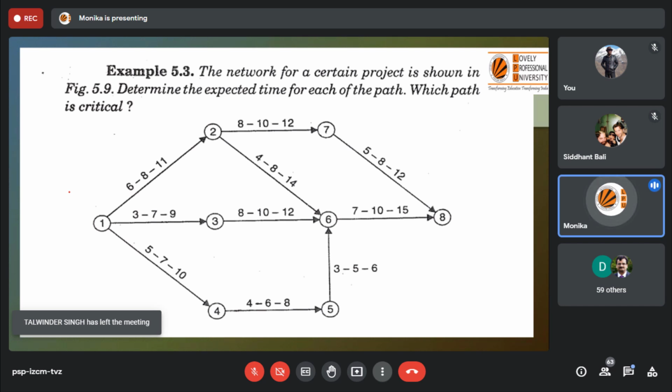Because sometimes everything is in favor of a particular activity. That's why we are not considering the whole project; we are considering it activity-wise. Sometimes it may happen that during concreting, all resources are available. Let us consider labor is available, materials are available, and all machinery is in place. Despite the 3 days we have given to the concreting operation, we are able to complete it within 1.5 days, because we have everything in favor of my activity.